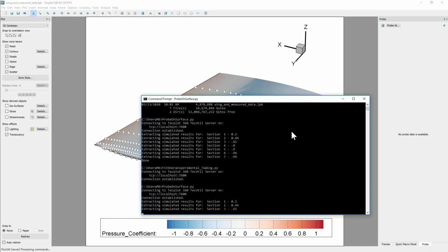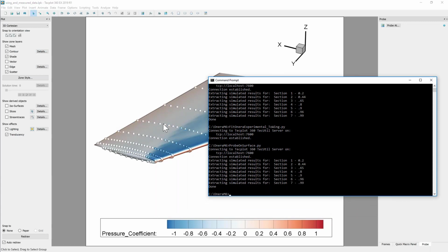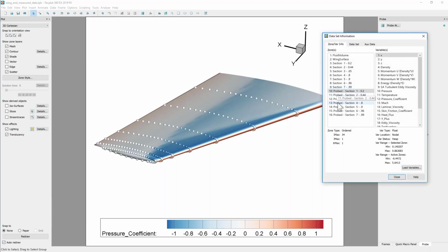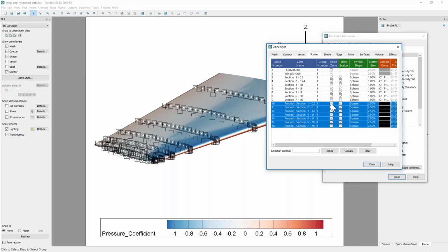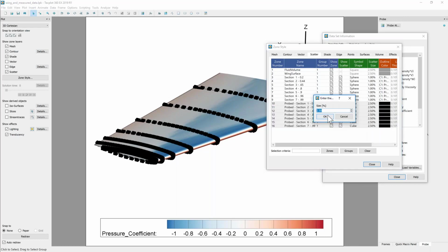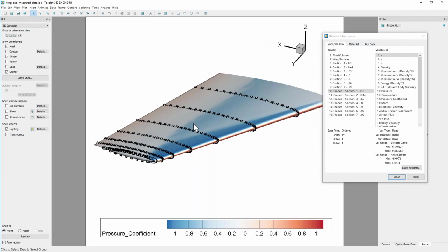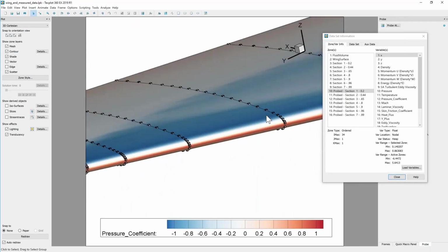And so what this is going to do is each one of these zones that defines the points, we're going to find the XYZ locations, and then at each XYZ location, we will call probe on surface and then construct a new zone within Tecplot. So if we go into the dataset information dialog, we now see that we have the probed values. So let's go into zone style and we'll turn these on. We'll change the scatters to cubes, and let's change the size to 1.5. And so now you can see that these are fairly coincident with the spheres. So we've found locations that are awfully close.